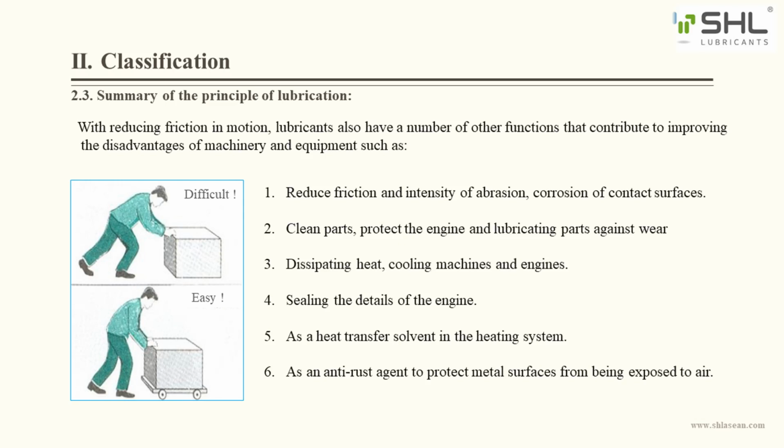Next, it also helps to dissipate heat, cool the machine and engine, prevent overheating of components, reduce energy consumption of equipment, and seal engine parts, as lubricants can fill gaps that cannot be repaired during machining. It is also a heat transfer solvent in heating systems, and an anti-rust agent that protects metal surfaces exposed to air. To ensure that the lubricating oil can perform all of the above functions, the lubricating oil must be of